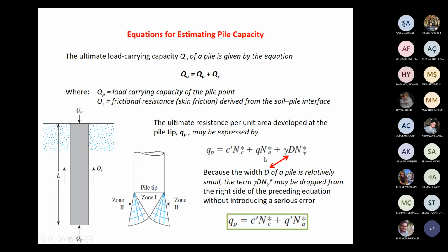The second term is q and Nq. This q comes from surcharge or soil stress at the depth of the foundation, which means the length of the pile.